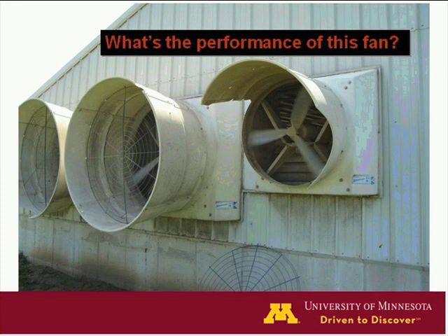Also, you want to make sure if you have those cones, they are maintained and kept in place. In this particular case, the fan lost that capability, and we really don't know what the performance of that fan is that had most of its discharge cone moved.